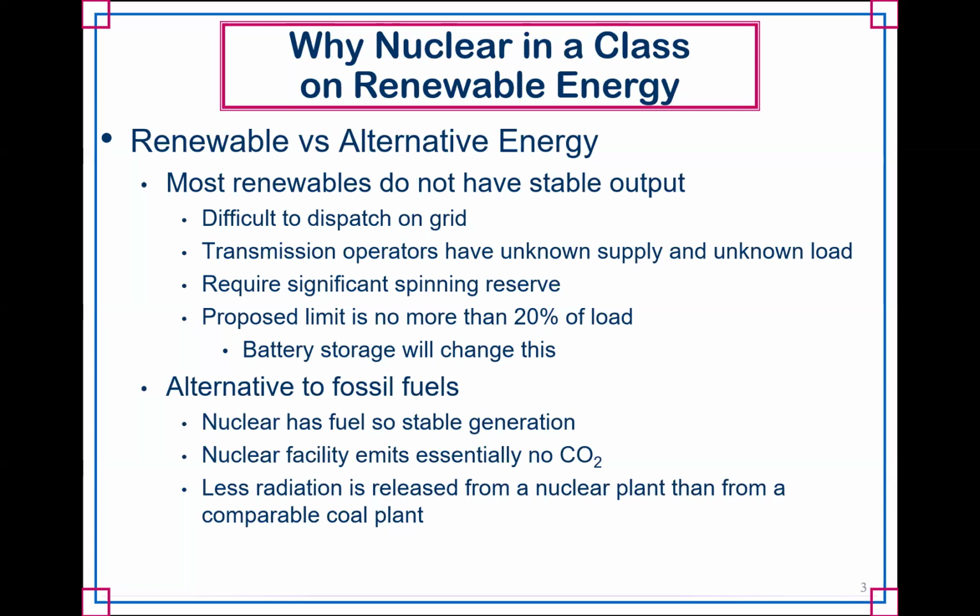And the concept of spinning reserve is probably getting a little bit antiquated at this point, but it used to be that if you had a generator and it was, let's say, a 100 megawatt rated generator, you might only run that at 70 or 80 megawatts. And the reason being is because the generator is spinning. In the event that something happens on the grid where there's a big increase in demand for one reason or another, then you have some generation that is spinning. It is ready to go to be able to very rapidly pick up and support that load. So that's the concept of spinning reserve, because the generators are already running. You don't have to wait hours perhaps to get those generators running. These generators can essentially put out the power you need almost instantaneously.